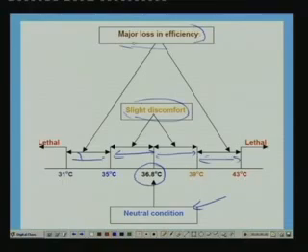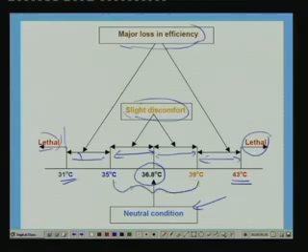If he is performing any task, he will be performing it with very low efficiency. So from 31 to 35 and 39 to 43. But when the temperature falls below 31 degrees centigrade, or when it exceeds 43 degrees centigrade, it can become lethal. It may even lead to death. So you can see that effectively the temperature of the human body, this is the core temperature, should always be maintained between about 35 to 39 degrees centigrade. Beyond that, it is not recommended, or it could become dangerous to the human being.